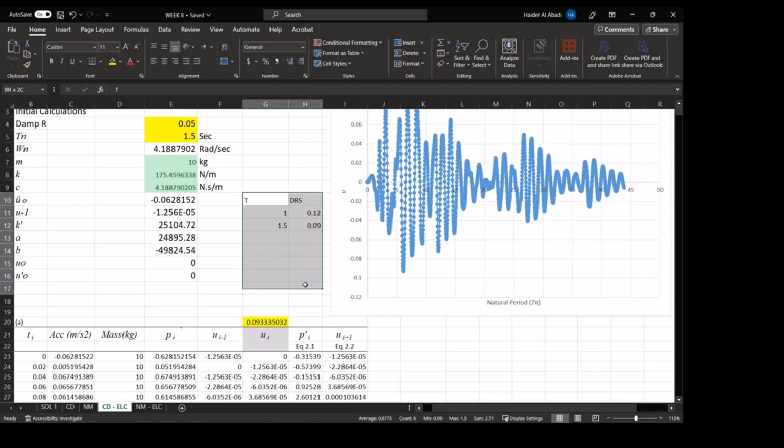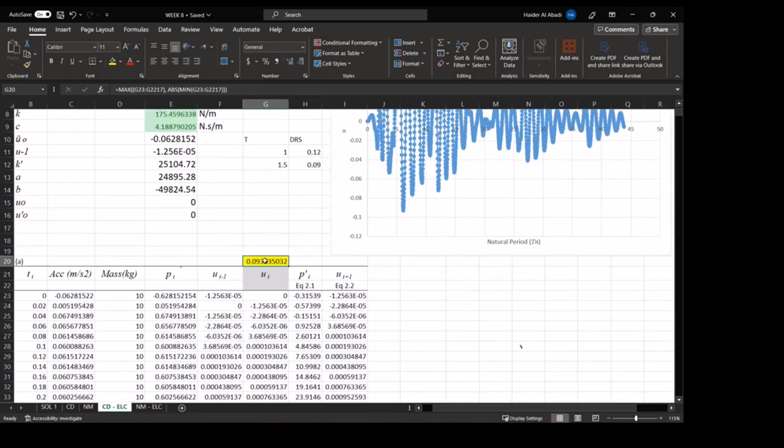After you do this for a range of time periods, then this will be called your displacement response spectrum, because you're kind of telling or plotting the spectrum of displacement responses for that particular system or building, whatever it's going to be. Your assessment is going to be the building you practiced. Is there any question about what I did with this calculation here?